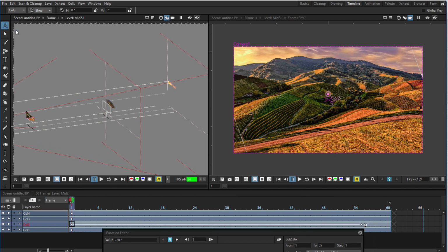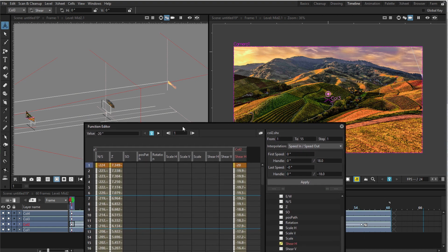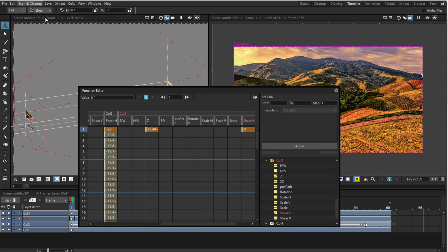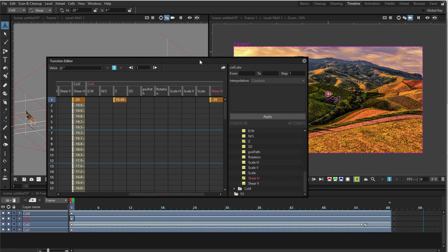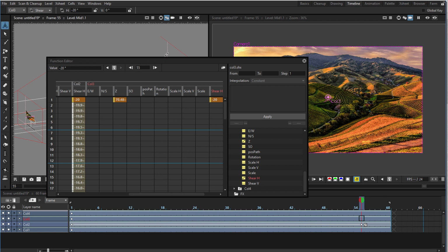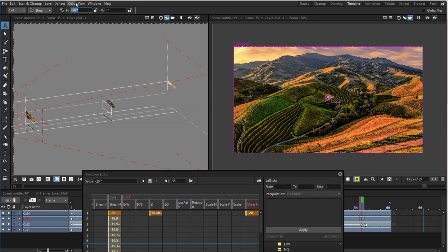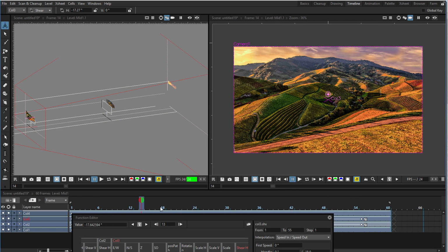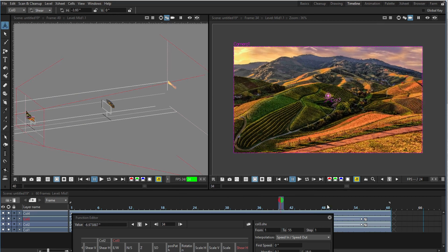So we're going to move to the next one, and we're also going to do, oops, I forgot if it's minus or plus. Okay, it's minus, I guess. Yeah, it's minus. So let's go to column 3, and let's set shear horizontal to -20, enter, and it's there. We're going to go to frame 55. We're going to change this horizontal shearing to 0. Again, if we now scroll through our animation, we can see this fake rotation going on.